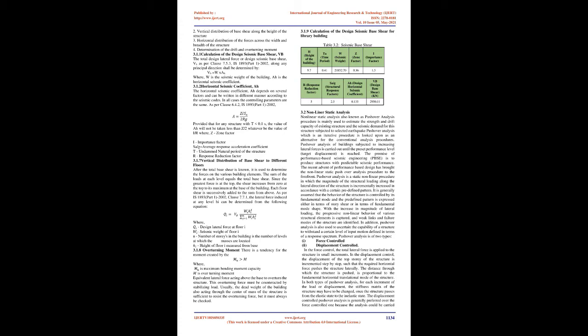Pushover analysis produces a pushover curve or capacity curve that presents the relationship between the base shear, V, and roof displacement, delta. The pushover curve depends on the strength and deformation capacities of the structure and describes how the structure behaves beyond the elastic limit. Nonlinear dynamic analysis is a principally convenient approach. In this, the structure is subjected to real-time ground motion of an earthquake, which determines the seismic response of the structure. The time history method can be applied to both elastic and inelastic analysis.